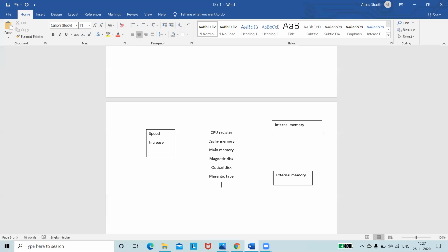Then greater capacity, slower access. Going down the hierarchy, the cost per bit decreases, capacity increases, and access time increases, and frequency of access by the processor decreases. So there are several important characteristics needed in designing a memory hierarchy, like inclusion property, locality of reference, and definitions. Upper means the memory closer to the processor.